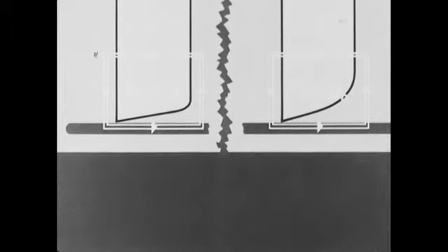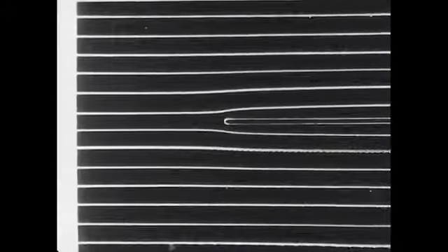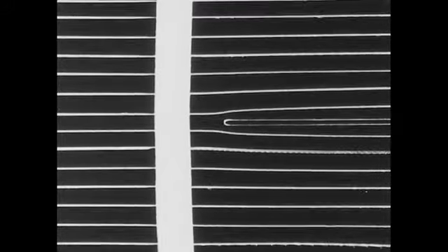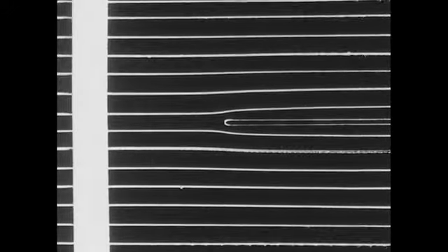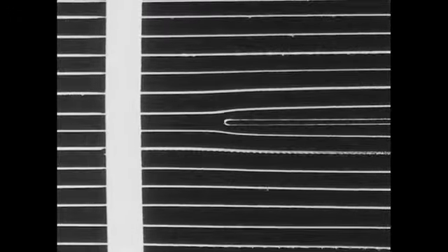The total amount of vorticity within each contour is the same. Because there is no vorticity upstream of the plate, and because the circulation per unit length along it is constant, we conclude that all of the vorticity in the boundary layer is introduced at the leading edge. But the distribution of vorticity normal to the plate changes along its length.